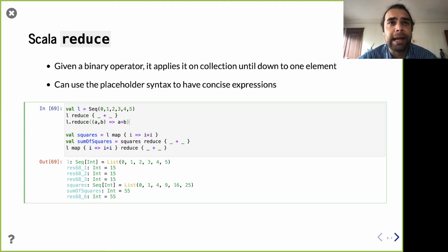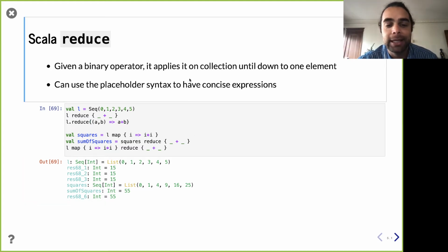If you dig around the Chisel standard library, you can see some places where they really wanted a tree. Actually, I believe for the OR reduction, other than comparing to zeros, you see them doing a tree, as a kind of recursion, halving the number of elements each time. It's not impossible, but it's more complicated than you first expected. Cool. Wow, a lot going on. But good, I'm happy to have the conversations. This is great.